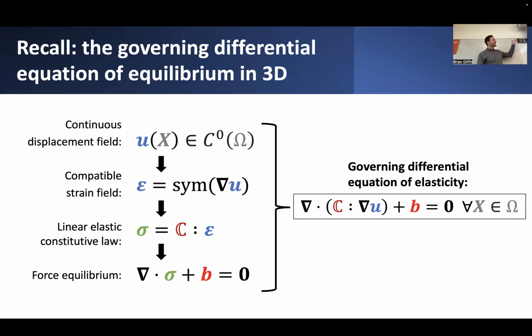In the case of this now more general three-dimensional context, you can still have a continuous function defined over some more complicated geometry, a 2D or a 3D domain. So the notion of continuity of functions still applies in that context. But we had to come up with more general descriptions of what displacement meant. Displacement wasn't just axial displacement in these one-dimensional problems. Now, displacement is really a vector of components of displacement which might occur in the x, y, or z directions.